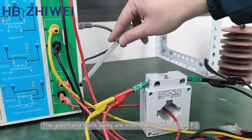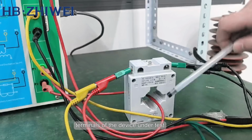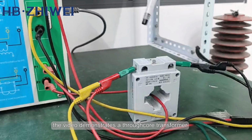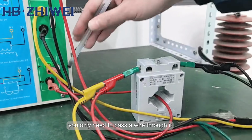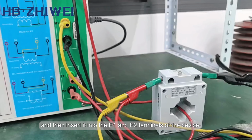The green and black wires are inserted into the P1 and P2 terminals of the device under test. The video demonstrates a through-core transformer. You only need to pass a wire through it and then insert it into the P1 and P2 terminals of the device.